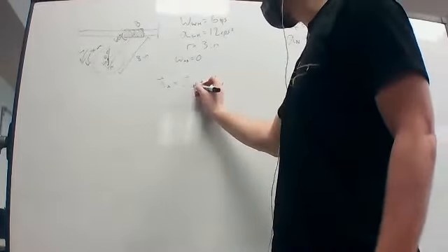And funny enough, you would think that if this arm were connected to the center, as the wheel moves this way, B would move with it as well. But since this arm is off center and below it, as the wheel moves this way, this centerpiece is going to move upwards. And as that moves upwards, it's going to have to force B to the right in order to keep its stiffness. So that's why we say AB is going to the right.